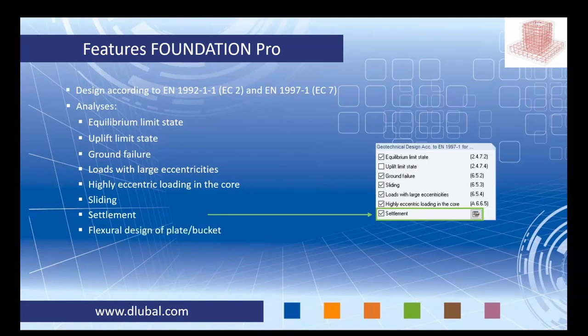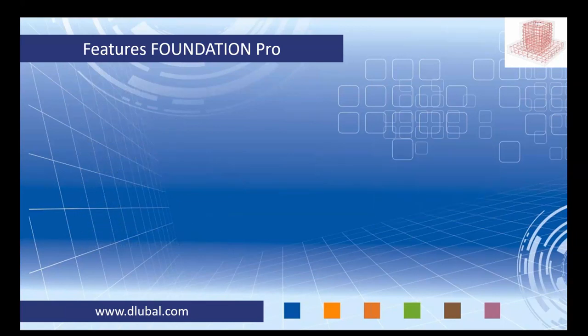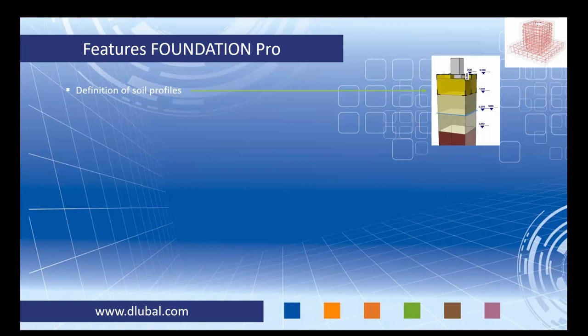And for the concrete design, we do a flexural design of the plate and the bucket, and also a punching shear design of the plate. What we can do in Foundation Pro is, for example, define soil profiles. As you see on the right side in the picture, we can define several layers of soil with groundwater for the geotechnical analysis and the settlement calculation.